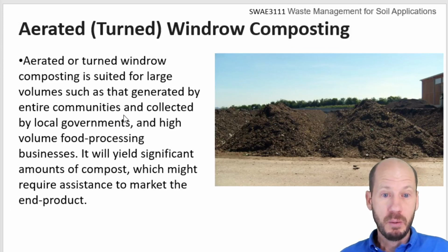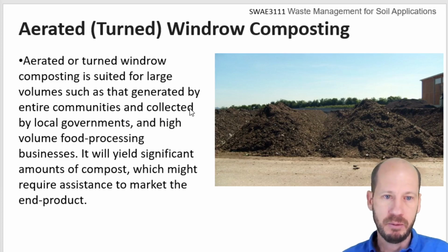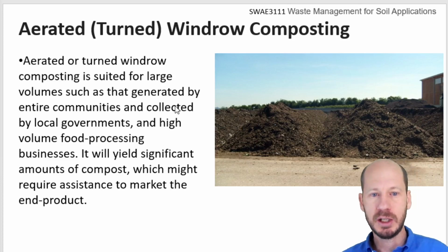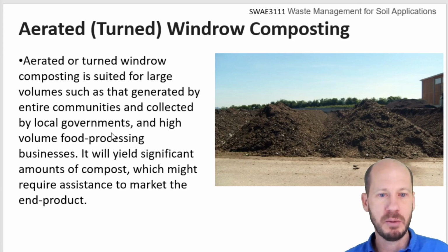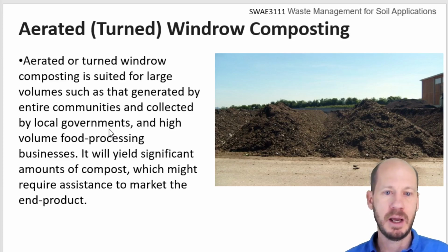The most popular way of doing compost, nonetheless, is aerated windrow composting. This is a larger scale type of composting, which means that we are building rows of piled up material, and we are turning this constantly or every few days. This is the same type of composting that we demonstrated on the field visits for the Higher Water Kala compost and the Al Haradi composting facilities.